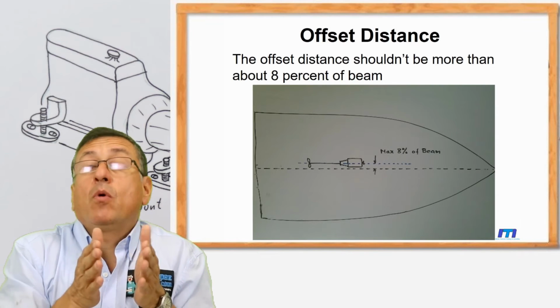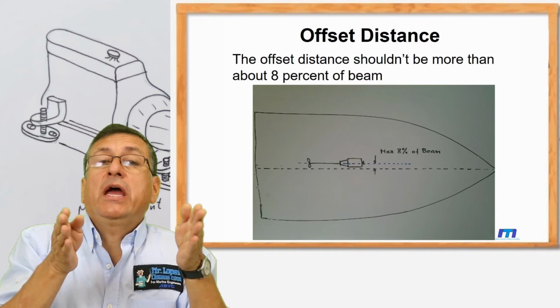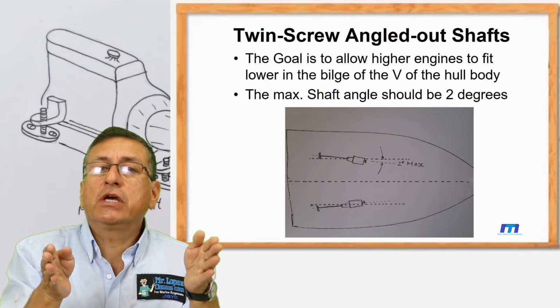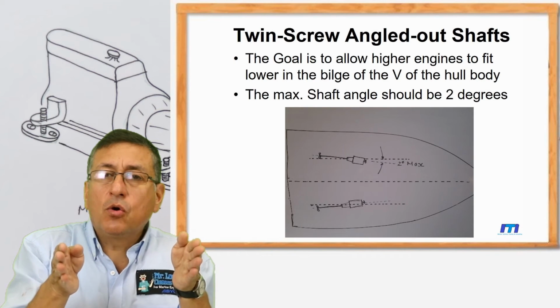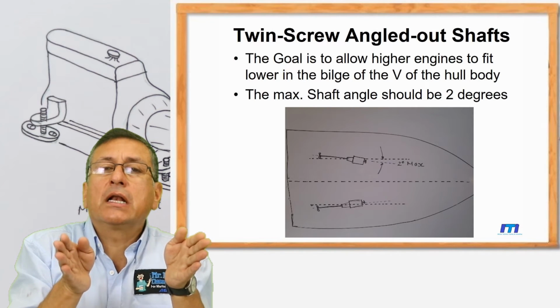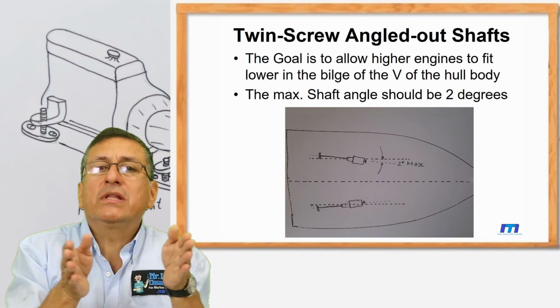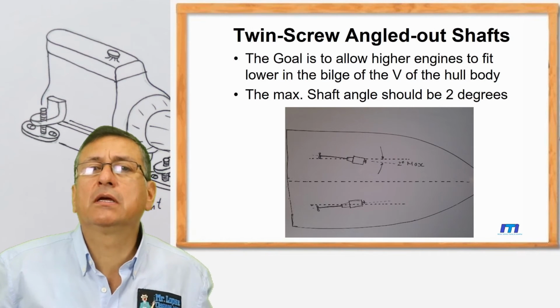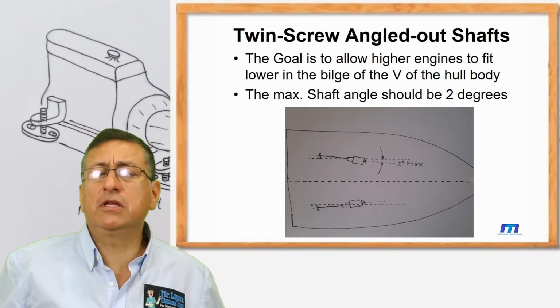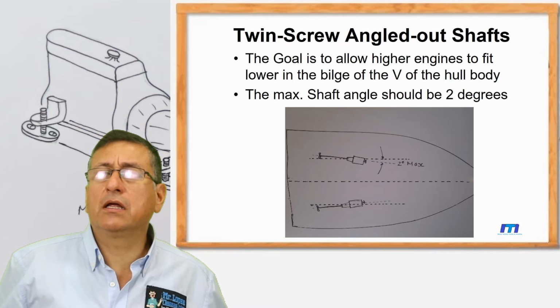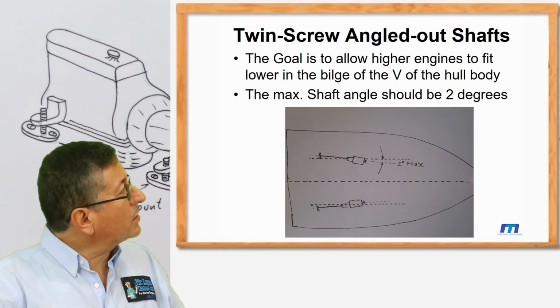And what happens if I have two engines, twin inboard engines? Those engines should be completely parallel or a little inclined, at some angle. What is the maximum angle recommended? What is the maximum separation recommended? I follow the rules of David Gerr in his book on propulsion systems, and those are his recommendations.